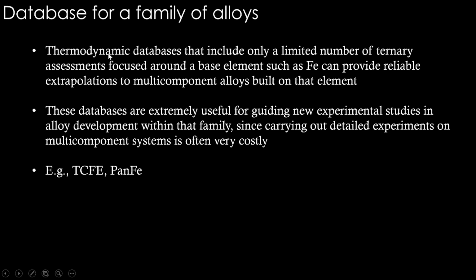Finally, one of the most important things about databases is that databases are made for a family of alloys. This is what is commercially sold. Thermodynamic databases that include only a limited number of ternary assessments focused around a base element such as iron can provide reliable extrapolations to multi-component alloys built on that element.